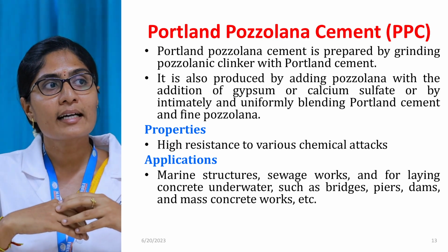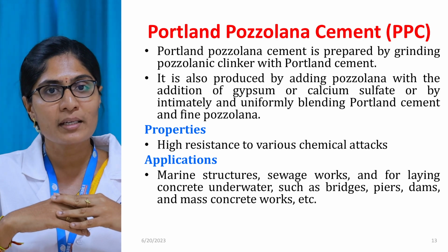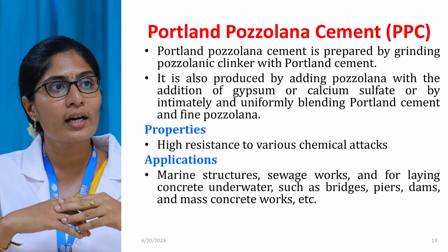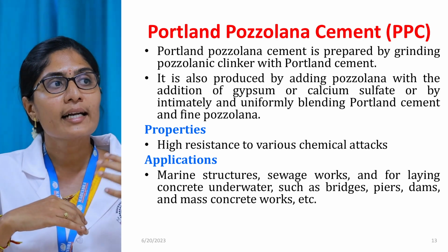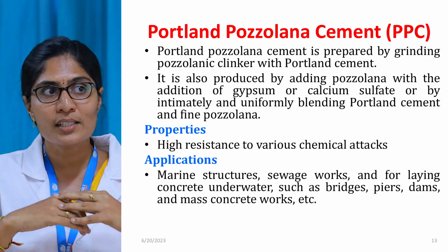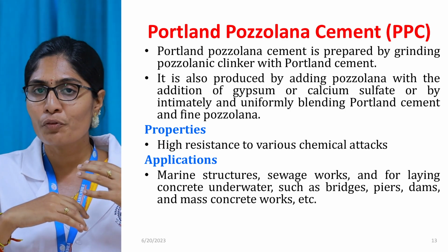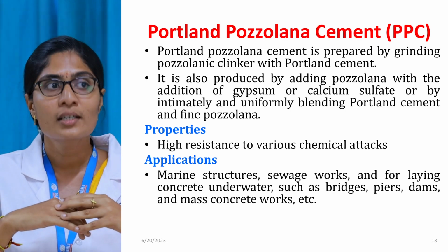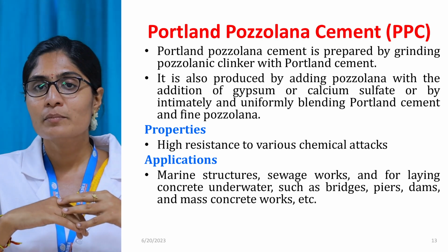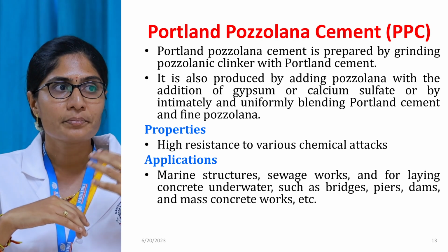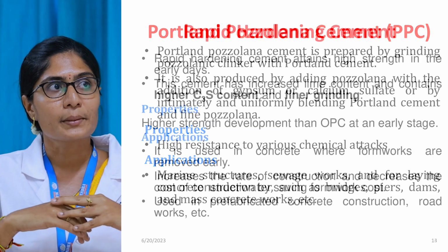Its properties are that it has high resistance to various chemical attacks like attack of sulfate, chloride, seawater, etc. And its applications are that it is used in marine structures, sewage work, laying of concrete in underwater construction, bridges, piers, dams and mass concrete works like retaining walls, etc.